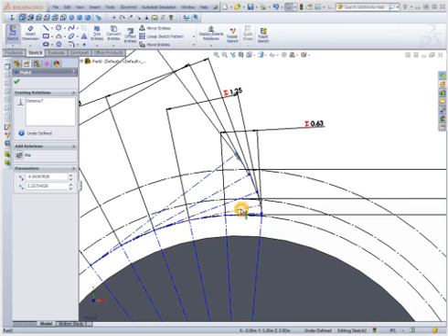Since we're drawing a single tooth, and half of that tooth actually, we need to divide it by 2 again. And that's going to represent this actual quarter length here. So it's going to be a sector length. It's not going to be the actual point-to-point length. And to actually figure out what the length of that sector is, we actually have to use a little bit different equation. Now, unfortunately, most CAD programs don't allow you to define the length of a curve. You have to define the radius of it. And so we can do that directly. We can actually draw a line intersecting with the vertical axis of our gear.